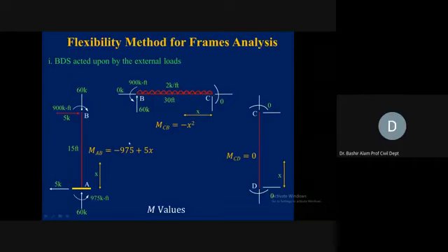So now at joint B, all the member actions are calculated. The vertical reaction is 60, horizontal is 0, and the moment is counterclockwise 900, which is coming from 2 times 30 divided by 2. Now this whole member is in equilibrium. All the boundary conditions are met.